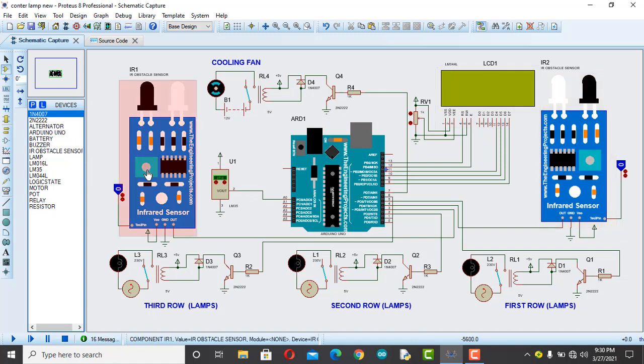Inside the code I've written that whenever the output of this sensor to the microcontroller is high, we increase a number to indicate that an obstacle is detected, and that's how it really works. So we count every single pulse of this logic state to represent that a person is entering or leaving the room.